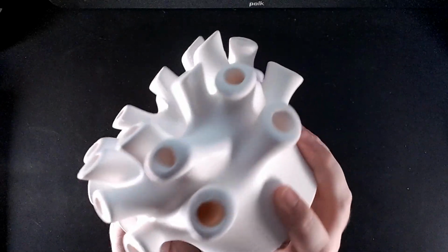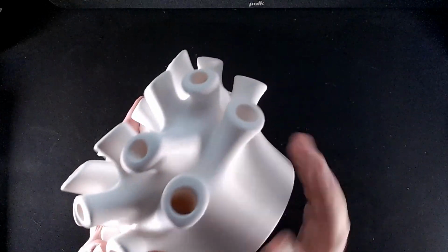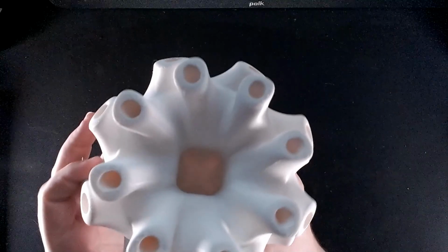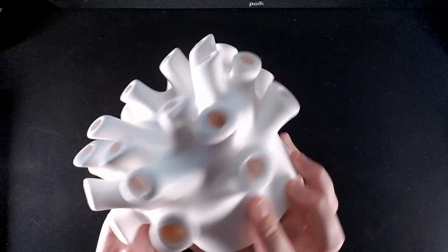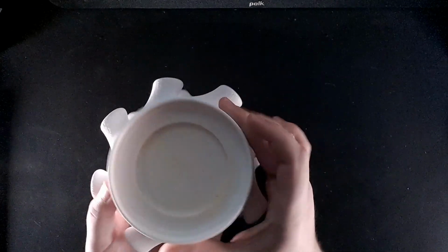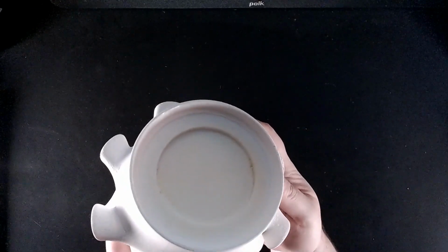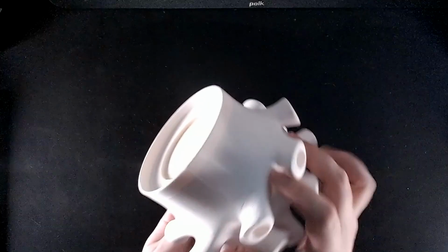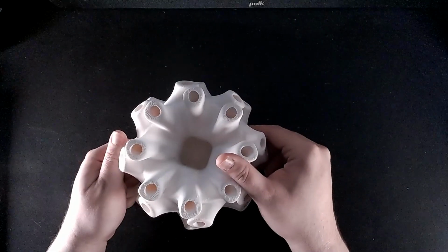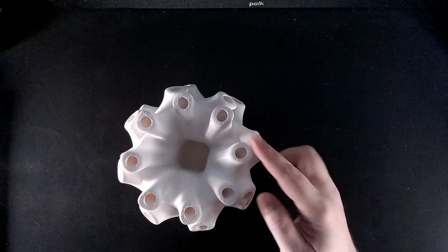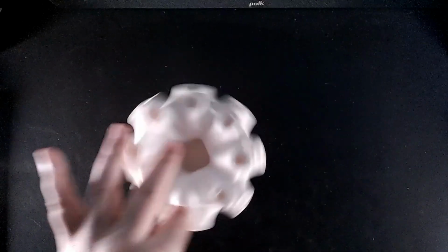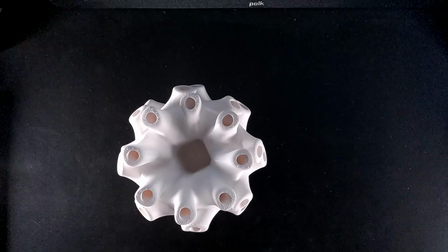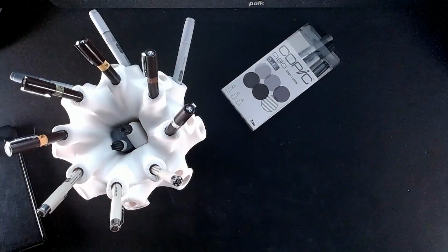All those surfaces printed out. Sure, it's FDM, there's a little bit of stepping. This surface would be absolutely perfectly suited to acetone vapor smoothing. I'm definitely considering playing around with some acetone vapor to see if I can't get these ridges to disappear. And there it goes. It's pleasantly smooth and about 5 inches in diameter.